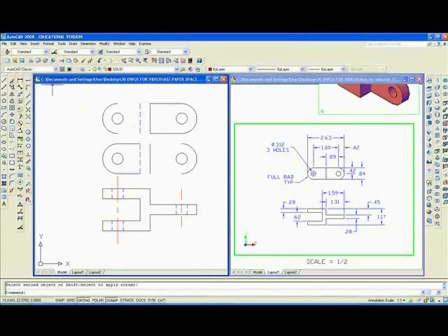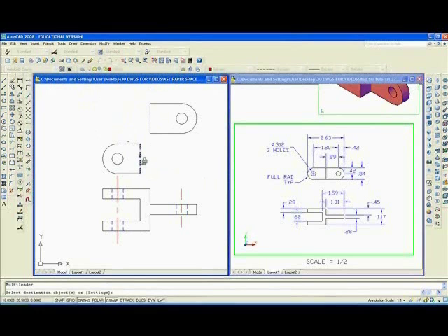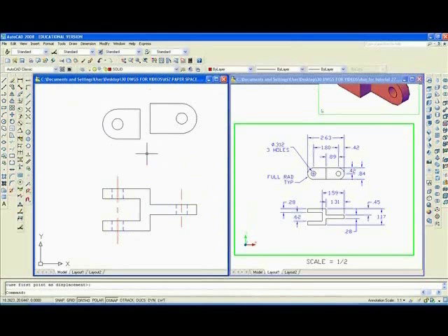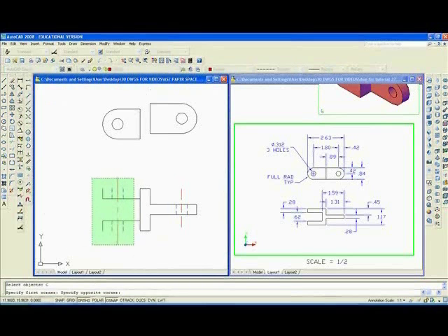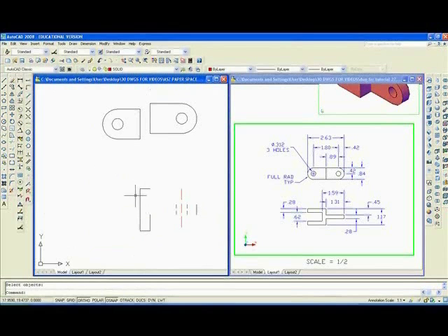I'll erase what I don't need and use a paintbrush, then I can move that piece back up again. Also, I'm going to need a centerpiece, so I'm going to type F-enter, fillet, and I'll fillet this portion here, which I'm going to need, and fillet this portion, which I'm going to need, and erase with a crossing C. Anything I touch is going to get erased. And I'll erase the other part here. And fillet this part, which I'm going to need.